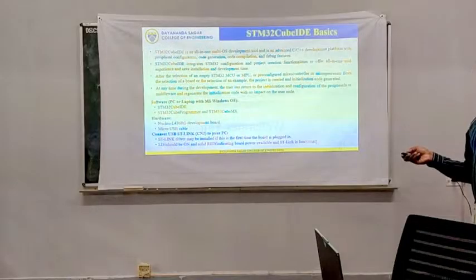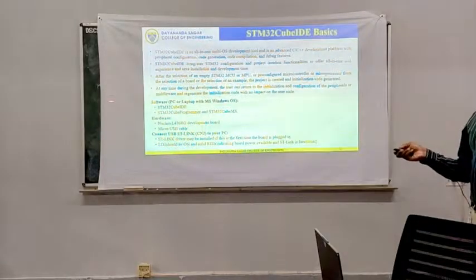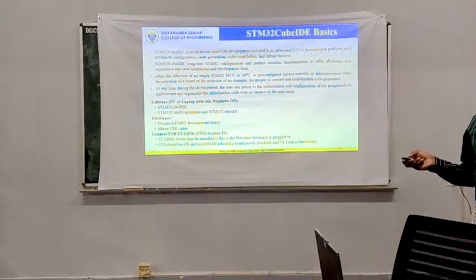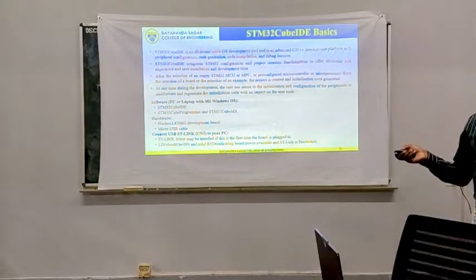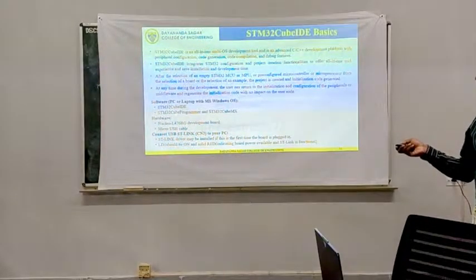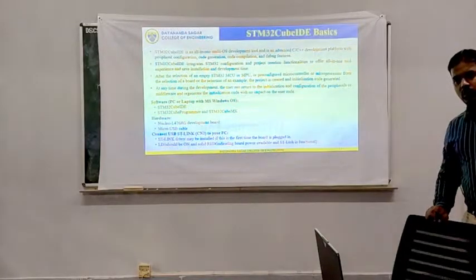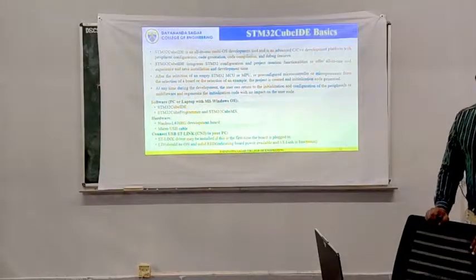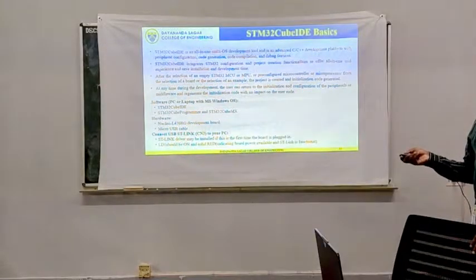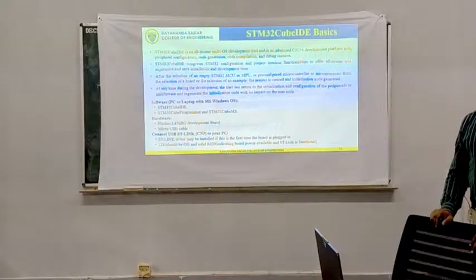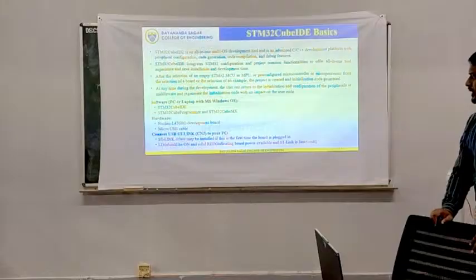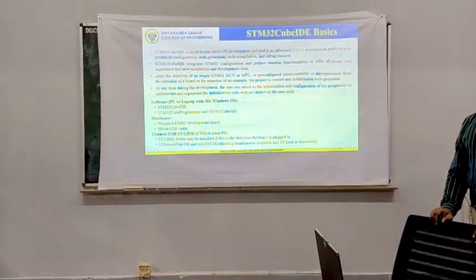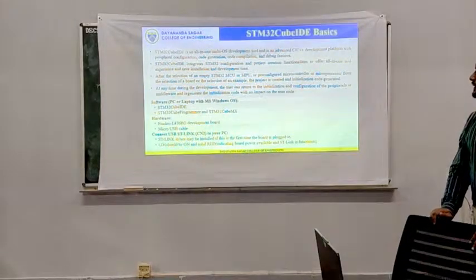For that purpose I use this STM32Cube Programmer. If you want to do any kind of internal setting change, we can go for this, but we are not doing any changes here, so this is not required. And if you want to do advanced level IoT projects, you want CubeMX, but we are not touching CubeMX here. The hardware I have given is an STM32 L476RG development board. Also one micro USB cable I have given, and it already has the ST-Link, so we don't have to connect any external ST-Link.